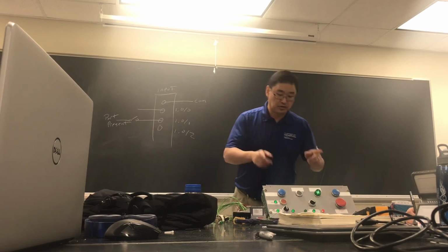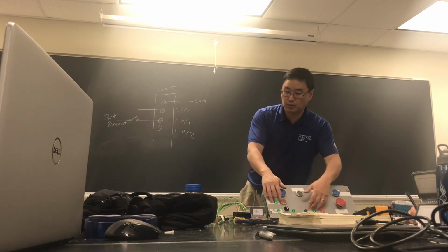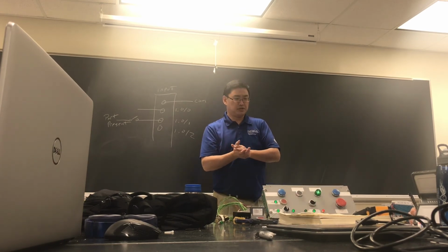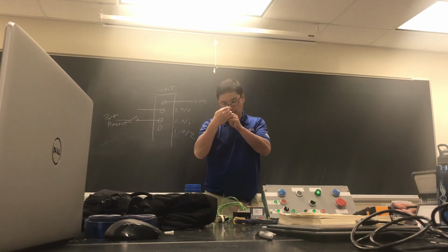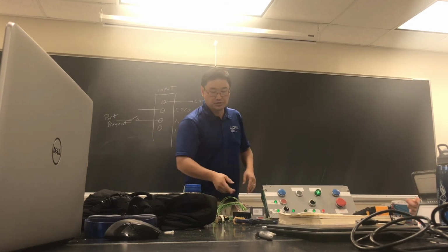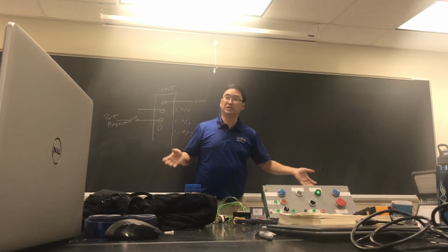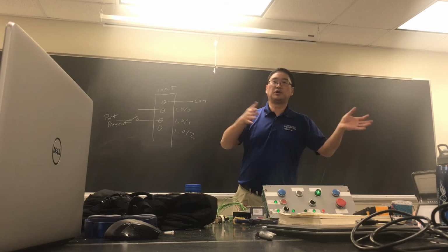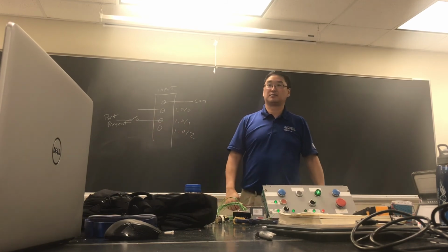No, all the lights are AC. So not only this one, but all the small ones are AC as well, I think. 120 AC. So any light is AC, everything else is DC. Make sure as you create your print, you're pointing to the right voltage on things.